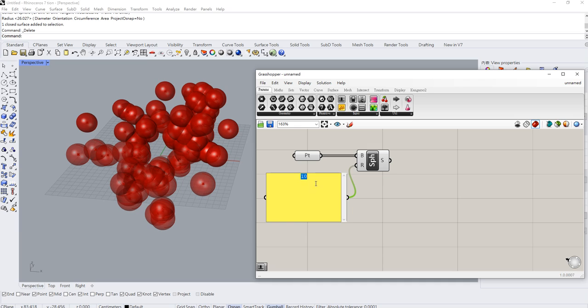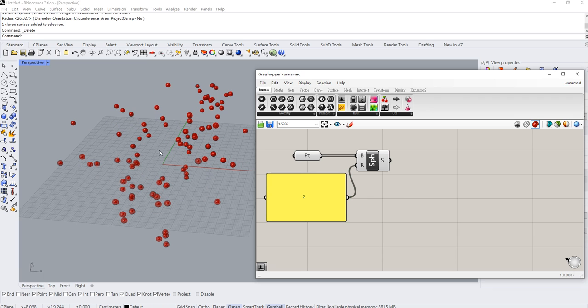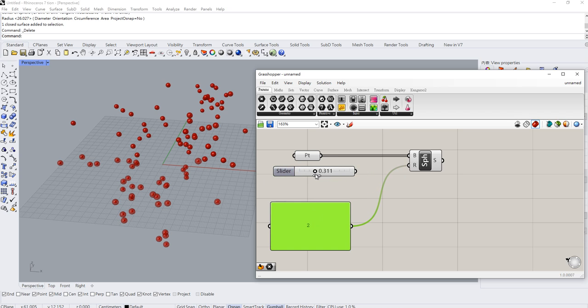But if you want to change the number, you have to do that again. You have to type in 2, and it will be smaller in response. But probably it's time consuming. So usually, in this part, I prefer to use a simpler way: the number slider. It's more intuitive and it has a GUI interface. Let's click this one. For the number slider, you can use your mouse to drag the number right here. So you can change the numbers this way. Just drag and then you can change.